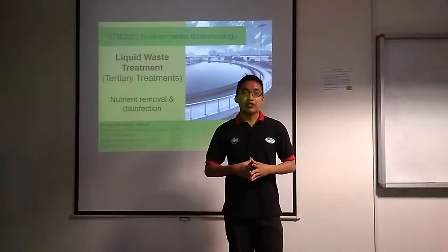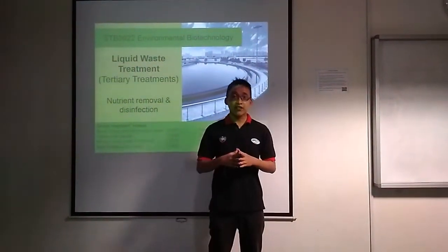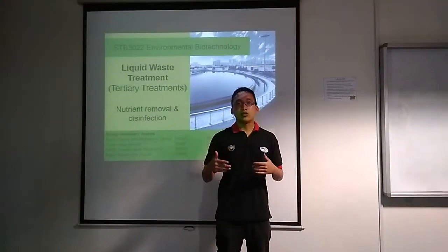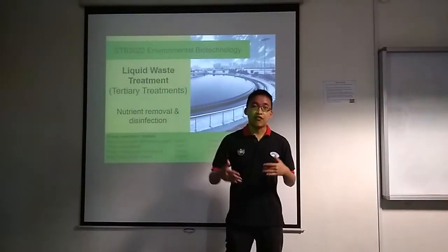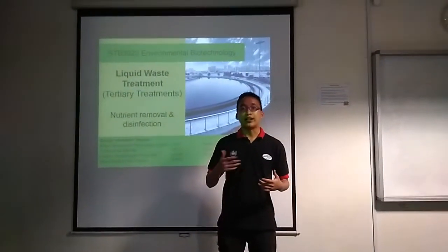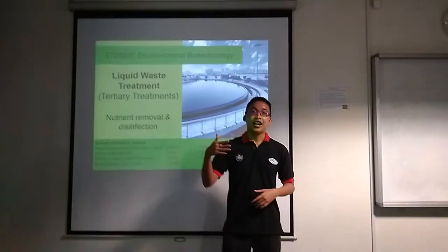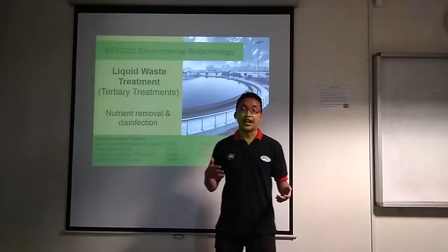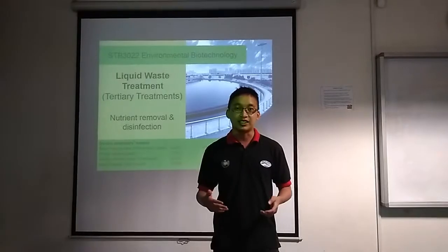Basically, what is tertiary treatment? Tertiary treatment is a final cleaning process which is needed to remove the nutrient content and to have disinfection of the water before the water is released to the environment, or either used as drinking water or even as recycled water.